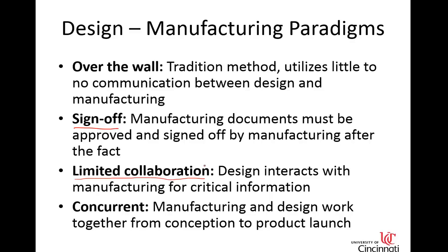What would it take to get this surface finish where I think I need it to be? And that's when the manufacturer says, well, if that's your requirement, you're going to need a grinding process. But if you loosen that up a little bit, we can do that on the machine tool, in the machine shop. So that limited collaboration can help you make some decisions, but ultimately the designer is still the one in charge and completely in charge and has the last say.